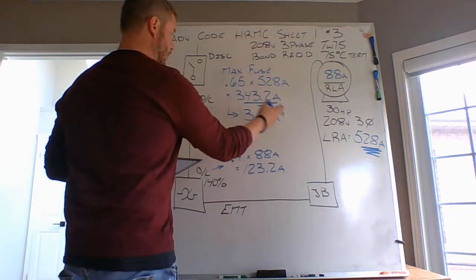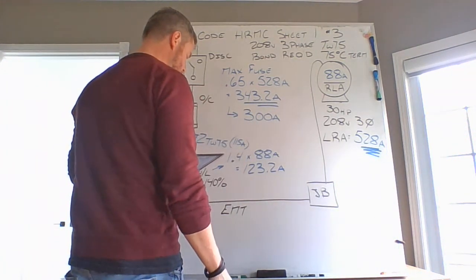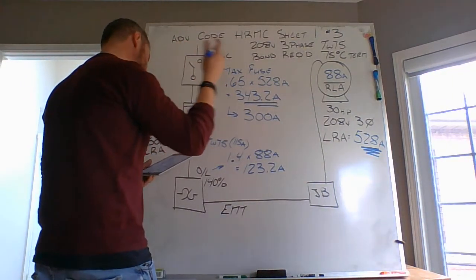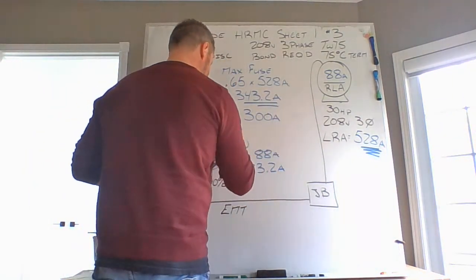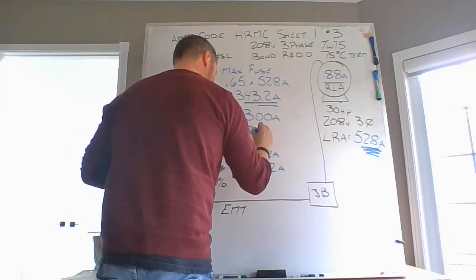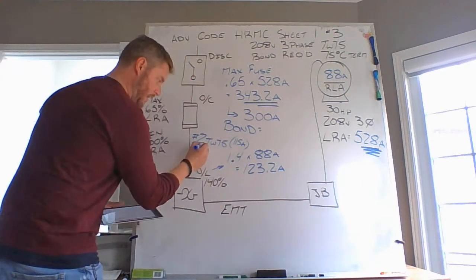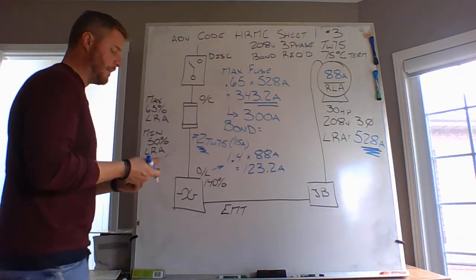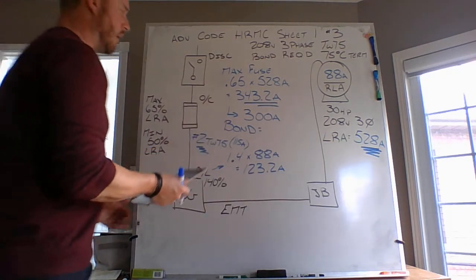So a 250 or a 300 amp fuse, doing the installation of number 2 conductors, going to table 16 for your bonding. At no point in time does it ever have to be bigger than a number 2. But looking at my overcurrent capacities, I can install a number 4.